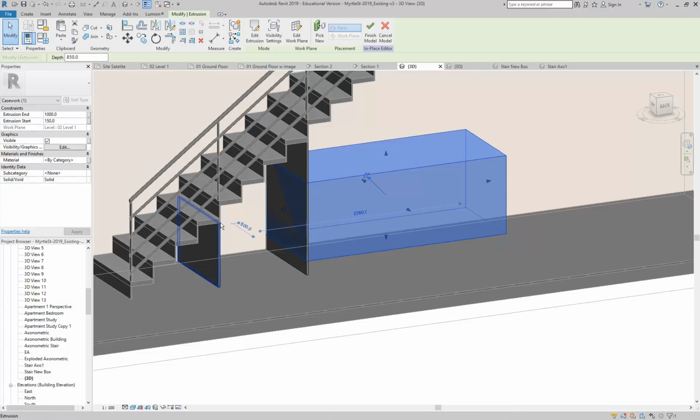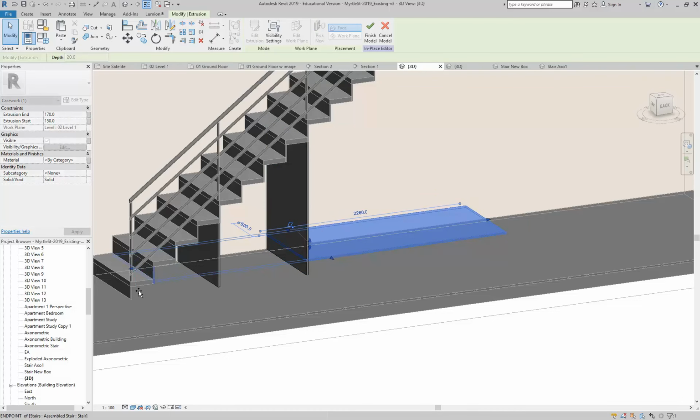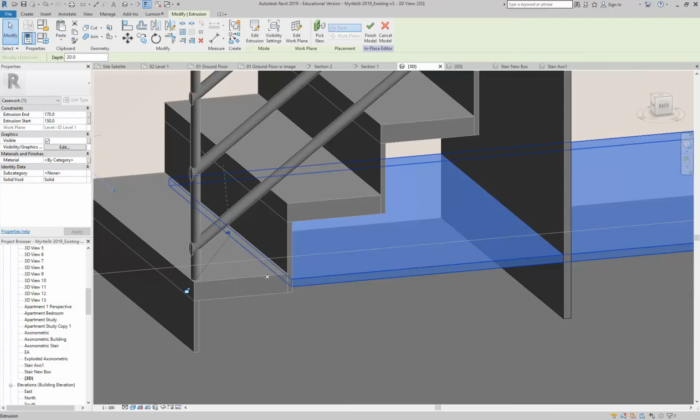Now here, if you wanted to line up with your steps, you might think about your riser height and use that for your shelf height. So it lines up exactly with your steps. But sticking with 150, if we want a 20mm thick board, what's the top going to be? You'd think it'd measure from the last one, but it's always measuring from the bottom. So it's always measuring from the same place. So it's 150 plus the 20. So 20 plus 150 equals 170. And then I'll stretch this across, and you can see it's not far off my riser height, but we can tweak that a bit further to get it to line up exactly.